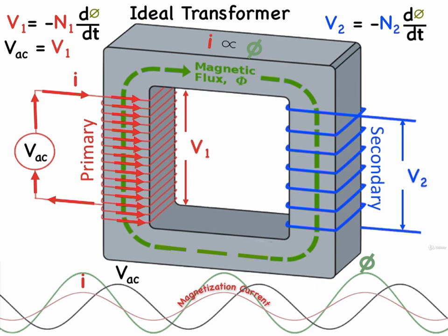In coil 2, the secondary coil, the voltage produced by that same flux by mutual inductance is also given by Faraday's law, which involves the same changing flux but times the turns in the secondary coil. That voltage is either larger or smaller than V1 depending on N1 and N2, the turns of the primary and secondary coils, but it is in phase with the applied voltage VAC.